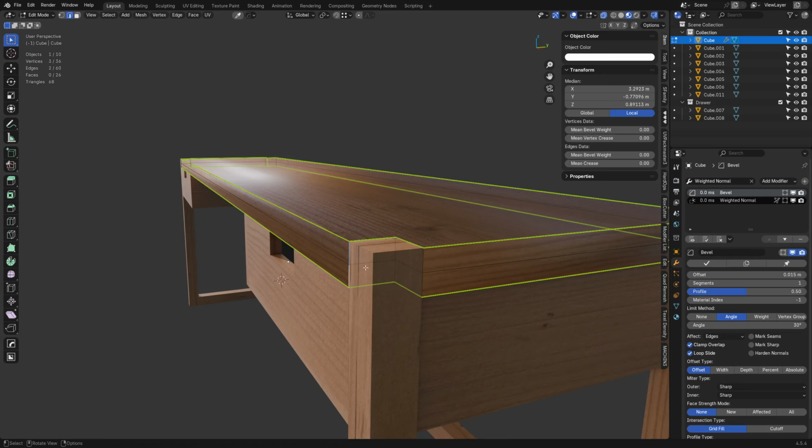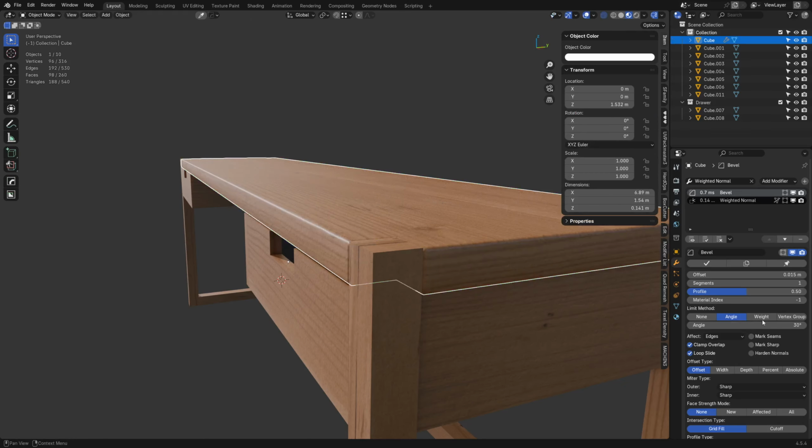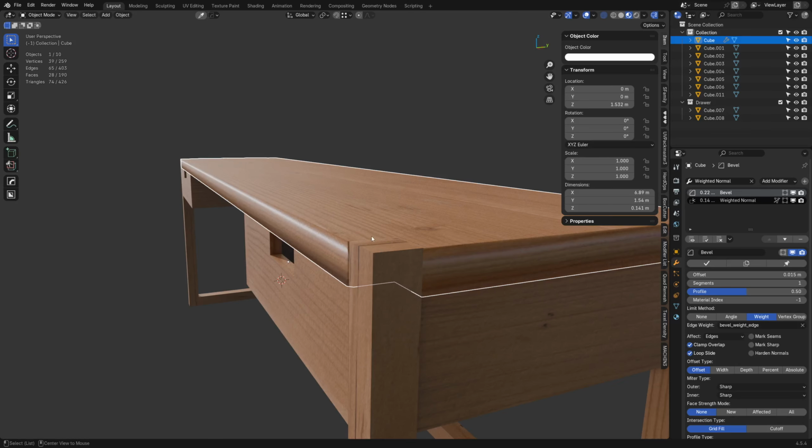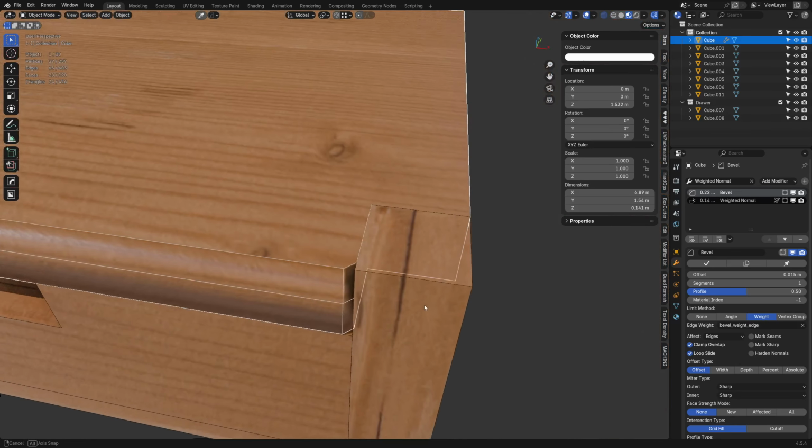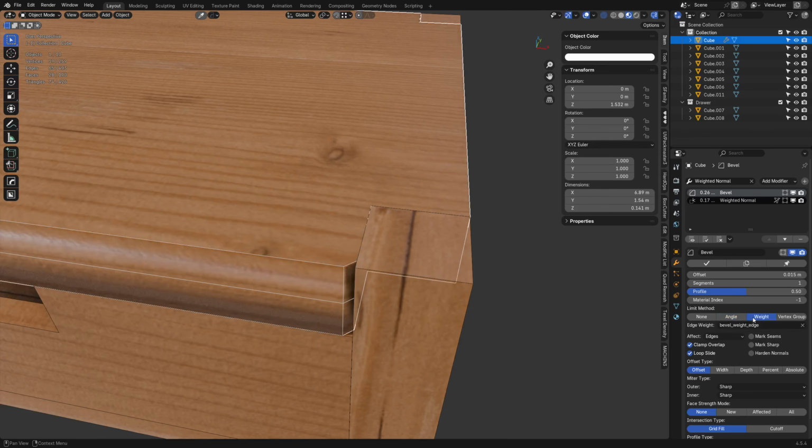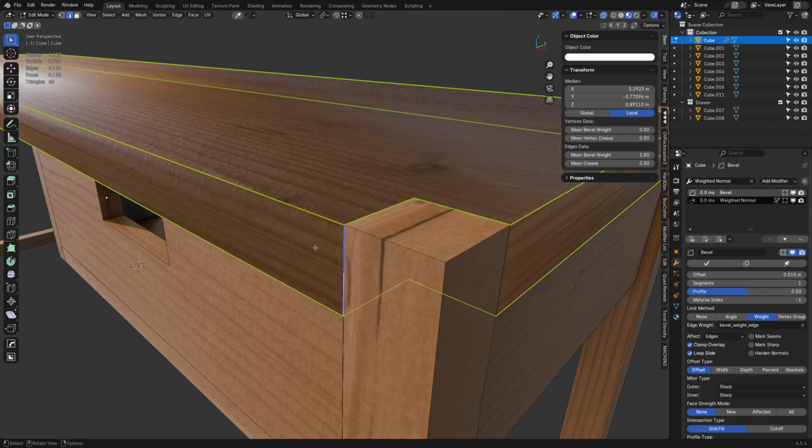So that would be just by selecting edges, pressing in, and using a bevel weight of like 1. Because if you're doing it uniform, you just use a 1, right? And so only the edges marked with a weight will bevel now. All right. So you'll see that one bevels in there, while none of the other ones do. So that's bevel weights in a nutshell. And then you would go around and mark every edge that you need marked.